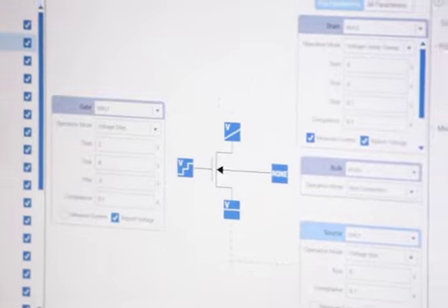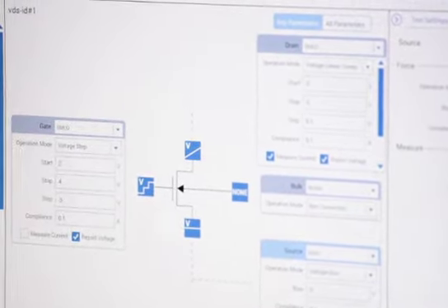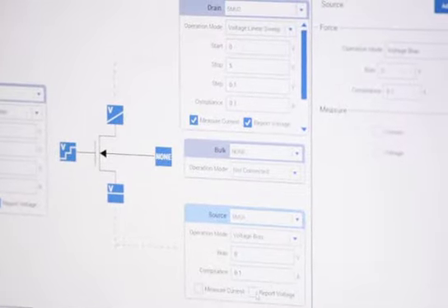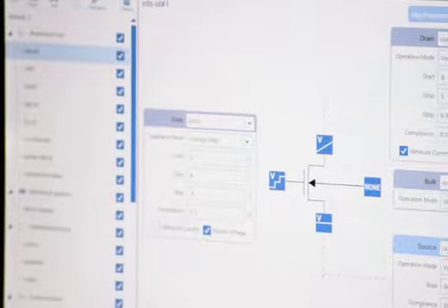You might see in some situations where it briefly goes into one of those sinking quadrants and then comes out. That's because of charge on your cables or on your device, and you might be changing from an elevated state to a lower state. That charge has to go somewhere. It's going to go into the SMU. Not only can it handle that, it'll tell you that. It'll let you know that it did that, and it'll measure it for you.